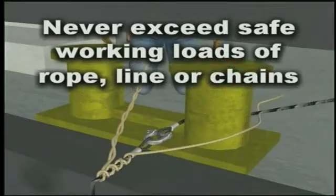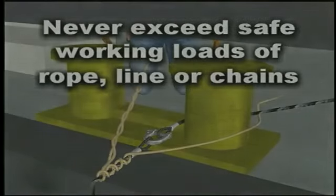The crew relied on manila rope as a stopper. The load on the rope exceeded the safe working strength of the rope. Never exceed safe working loads of rope, line, or chains.